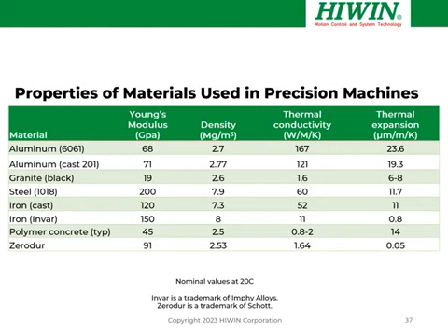Here's a brief comparison table of different materials that are often used in precision machines. So we have on the left-hand side a list of commonly used materials. And then we have some parameters: the Young's modulus, or the stiffness; how heavy it is going to be, and we often want lightweight structures; the thermal conductivity, is it an insulator or a conductor; and its thermal expansion, does the material expand a lot or a little? So you can see that there's not one obvious choice that is best in all parameters.